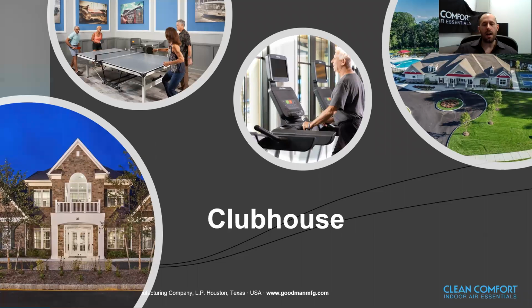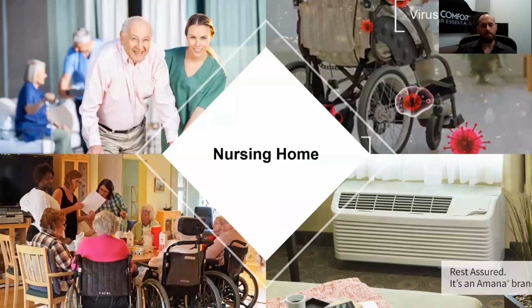Clubhouse. This is a clubhouse for active adults, and they didn't have an issue. They wanted to provide a safe and clean facility for the community. So we used small media air cleaners on the air handling units. We brought in ventilation and we added air purifiers. Now with this one, I want you to note that it is still in the design phase. This one has not been installed quite yet.